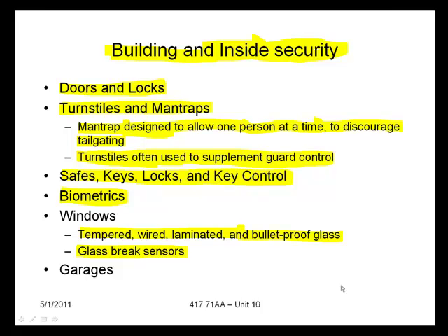Throwing a large brick at wired glass, or hitting it with a baseball bat, will shatter the glass but not knock it out. So it makes it harder for somebody to gain illicit entrance by shattering a glass window if it's got wired glass. Laminated glass is recommended for installing in street-level windows and other access areas. It's two ordinary glass sheets bonded to a middle layer of resilient plastic. It may crack, but the pieces tend to stick to the plastic inner material.